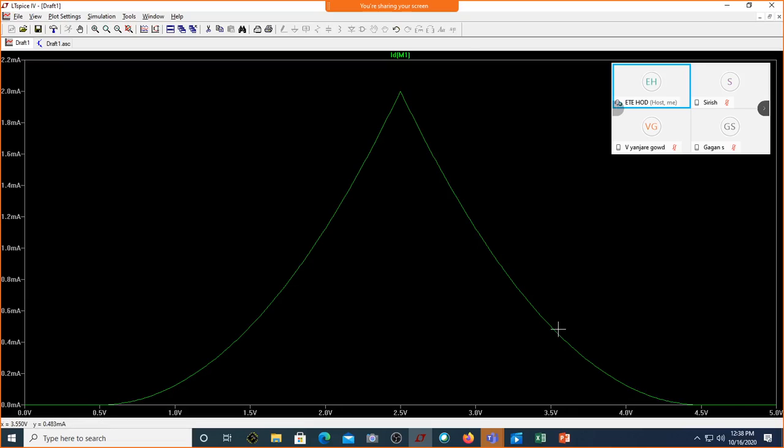Because of the threshold, sir. Because this is a CMOS inverter, and it is charging through PMOS first, the current rises; second, it falls as current discharges through NMOS.